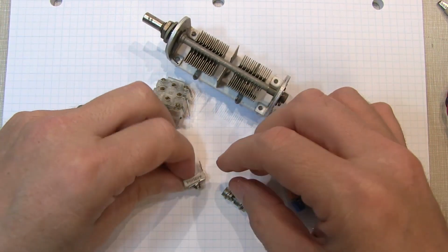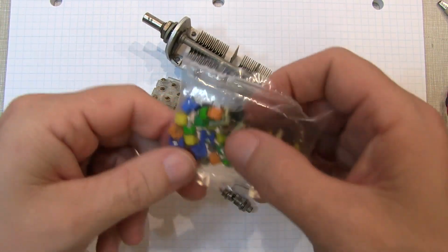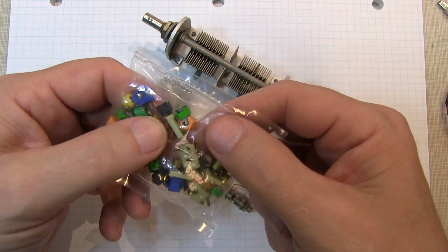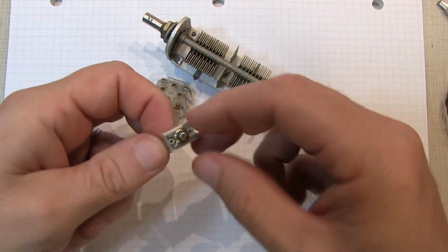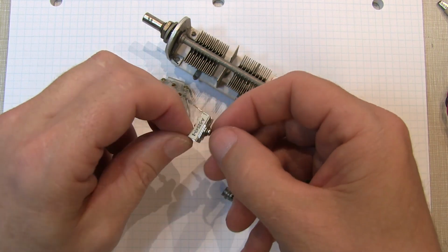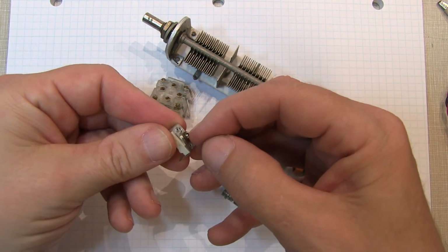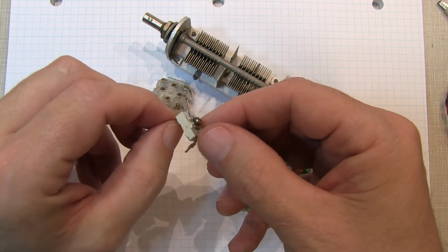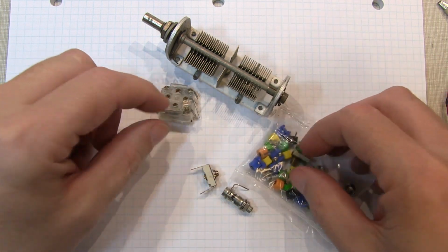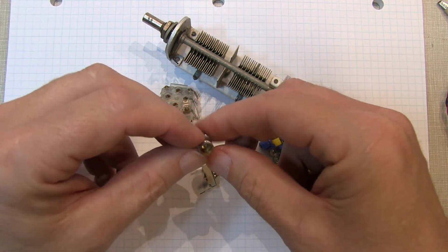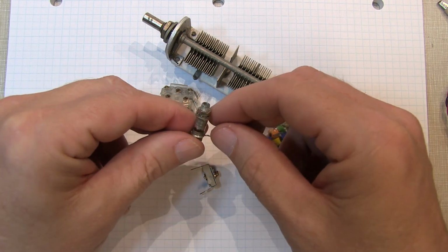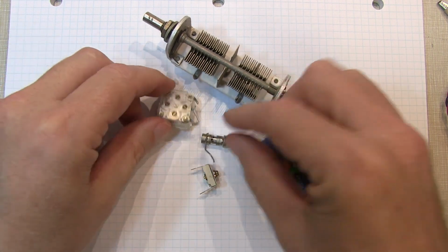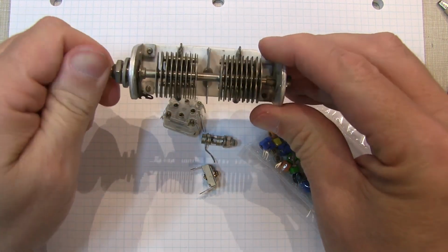Then you'll also have trimmer capacitors that might be small little ceramic type trimmer caps. I've got a bag full of different types here. Maybe some compression caps. These guys are basically two plates that, when you loosen the screw, the plates separate, and they'll often have a mica insulator between them. These types of caps obviously are all used in RF applications. Here's kind of a slug-tuned variable cap here as well. Lots of different types of variable capacitors that you'll run across.